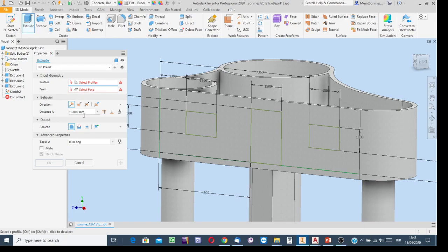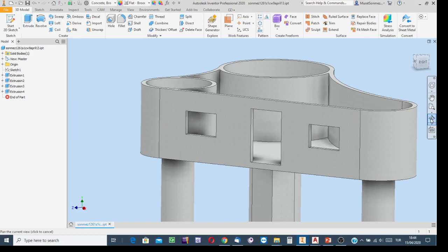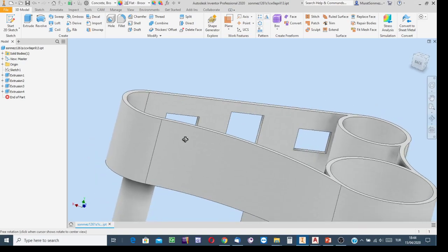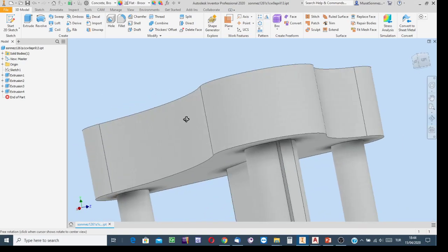is the correct process. Select the cutting option, and then for the rest, indicate the profiles, this and the other. Well, the thickness of the wall is 200, so as the cutting length, minimum, right, 200, and then say OK. Yes, here we are. We have a door opening and 2 window openings.